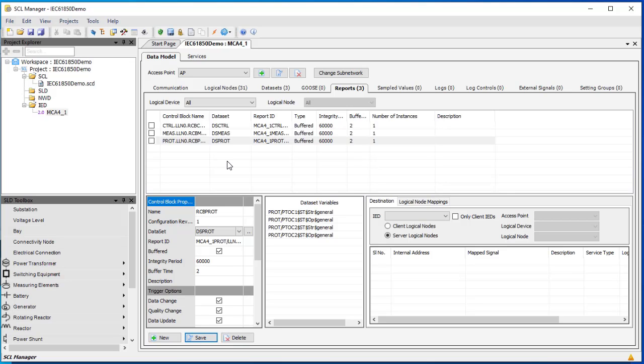for the substation communication. Very important to know is we are using dead bands for information. Dead bands mean if we have a voltage of 10,000 volts and we say we have a dead band of 100, then the voltage update will only be performed if the voltage rises above 10,100 volts or falls below 9,900 volts.